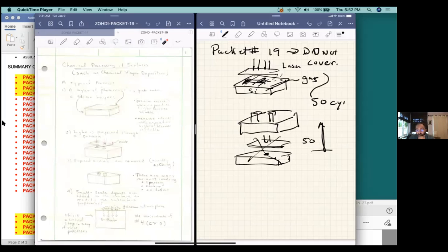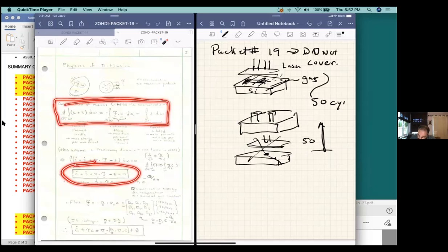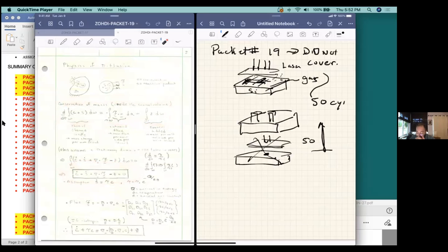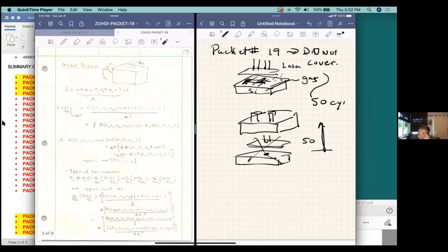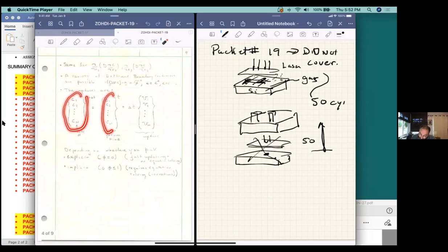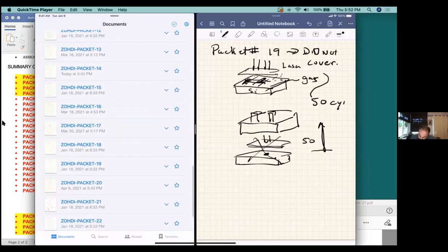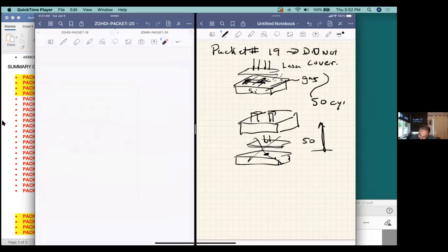So quality control in these methods is important. The governing equations for these are almost identical to the first law of thermodynamics. You end up getting a differential equation that in a formal sense is exactly the same. And you can, of course, then apply the same kind of numerical techniques for finite difference discretization in time and in space. If you do this properly, you can set this up as a type of spreadsheet calculation as well. So again, not covered in this class, but a topic of pretty high importance.